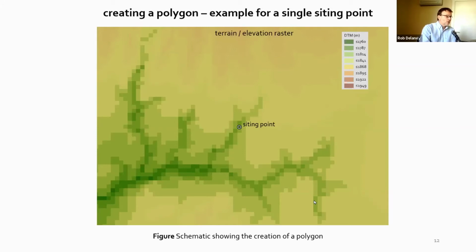So we also know the flow direction at that particular point, again from the analysis of the elevation data, and we use the flow direction, which is D8, which gives the eight possible options for any one cell. And the model then, once we know the direction of the flow, creates an access line perpendicular to this flow direction.